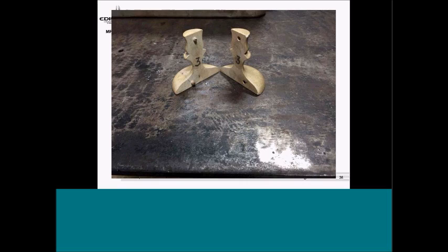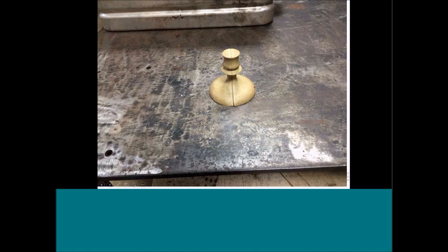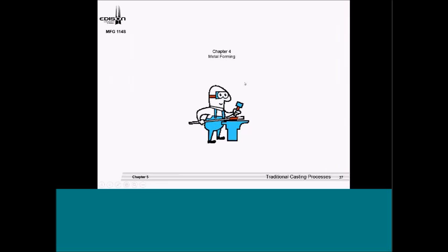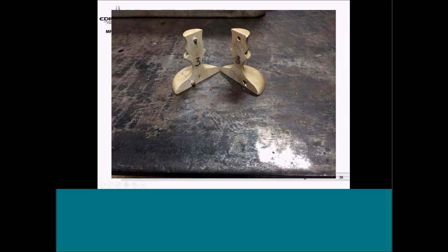I think I have a poor casting out there where it's not matched up very much. He's got about a 1/4 inch on this side and then missing a 1/4 inch, so it's stepped. What I like about this candle is after we pour it, and generally they'll pour it in pairs, then when we go to the machining processes, they'll face it off, and they'll drill for their candlestick. So it's something that they can have and take away. Okay. Any questions on the casting process?